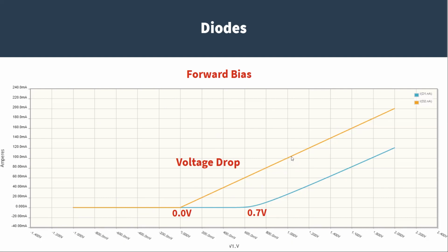If you remember, Ohm's law said resistance is the slope of the line, the ratio of voltage to current. Because of the junction barrier, the diode doesn't conduct until it's around 0.7 volts. It actually starts conducting around 0.6, and different diodes will vary. That's why it's an approximation.